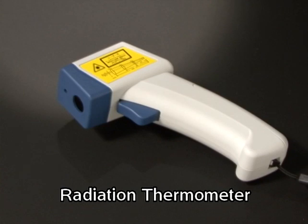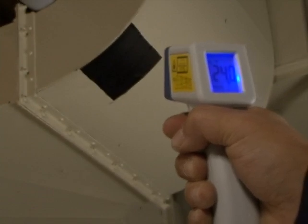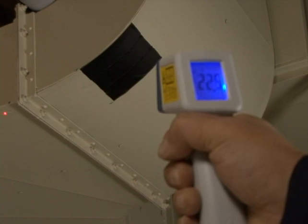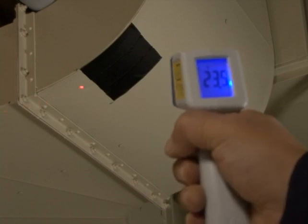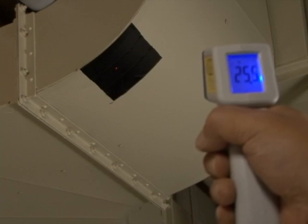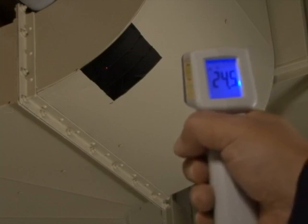The radiation thermometer measures temperature by measuring the intensity of infrared waves, a type of electromagnetic wave radiated by the object being measured. However, since the emissivity of infrared radiation varies from substance to substance, the value derived from measurement must be corrected to ensure accuracy. When it is necessary to measure accurate temperature, it is effective to apply a black tape or black paint of known emissivity.